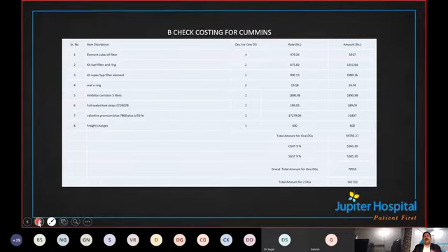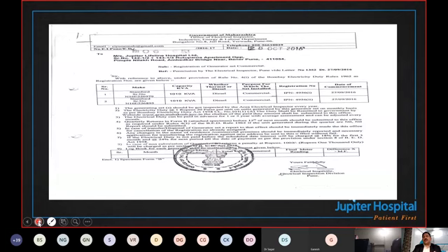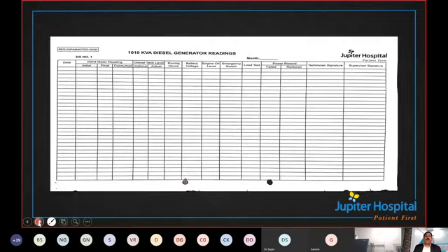Moving ahead, these are the government norms which apply when we are using this DG. These are the norms which have been considered. These are very, very important if you are running a DG, and every time you have to take a reading. Your in-house team has to maintain everything, right from battery voltage to engine oil, every day, so that you can understand whether the DG is running or not. A no-load test has to be done every time. So these things are very, very important.